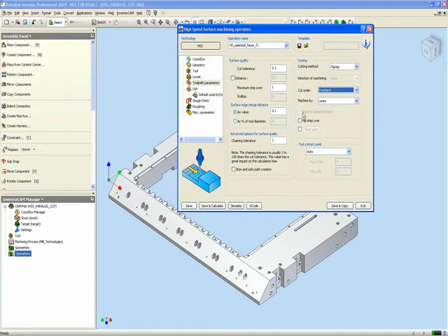Now we also have an option of machining by, as far as the ordering goes. We can either do by lanes. By lanes it'll go 1, 2, as you can see over here, and it doesn't make a difference if you have a break over here. It'll go from one area to the next. Or we can do regions, whereas in regions it'll first do the first area, then the second area over here, and then finish off the third area.